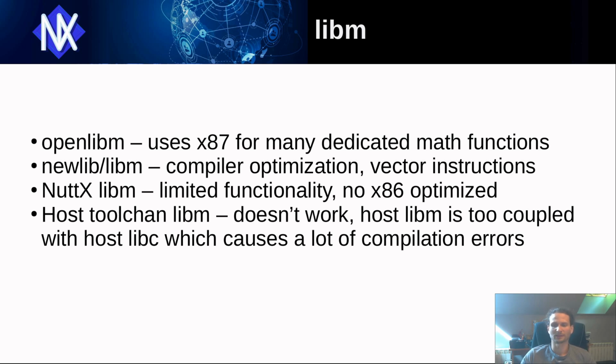The NuttX math library is also supported, but it has limited functionality and is not x64 optimized, so its use in real-world applications is limited. I also experimented with the host toolchain libm. Unfortunately, it doesn't work. The host x64 math library is tightly coupled to the host libc, which results in a lot of compiler errors.